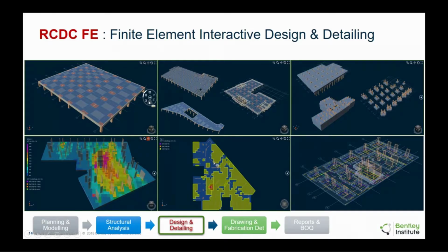A lot of tools to quickly change all of that. You click a button, let's say on this, and say regularize it from this jagged shape. It will automatically become a rectangular shape area and so on. So all of that exists, and then you can visualize what is happening in 3D during the design and detailing process. So since they are much larger areas and they are three-dimensional floor plates, you can actually see that. So you can actually see the mesh, the local extra reinforcement, all the anchorages drawn to scale during the process.